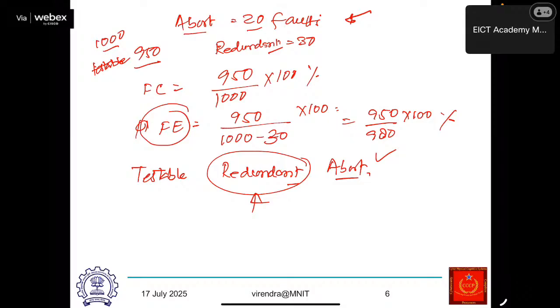Because in the worst case, to generate the test, it may need to explore all possibilities that can occur at the primary input. All possibilities are 2 raised to the power n, and if I say a circuit with 100 inputs, in that case 2 raised to the power 100 will consume something like several centuries, right?